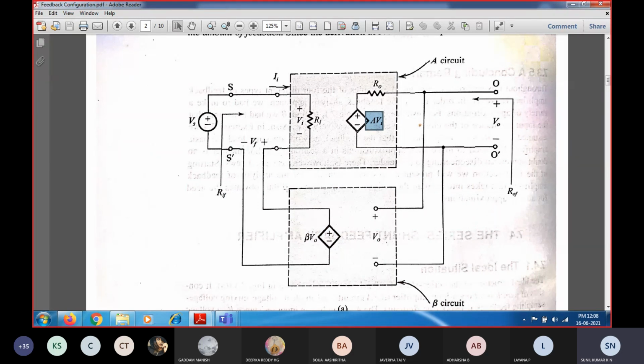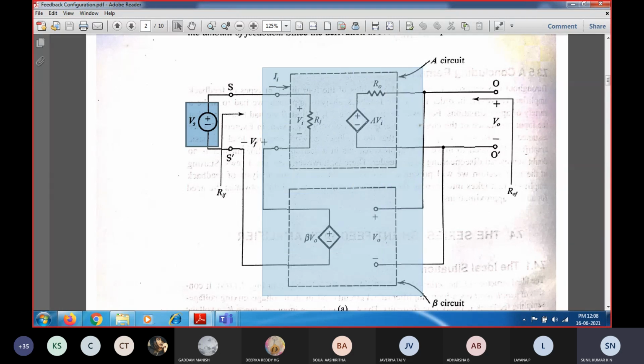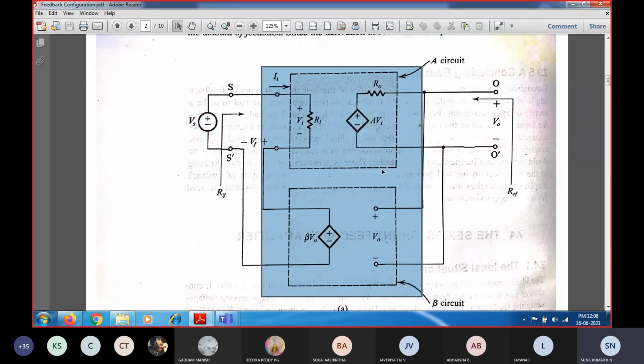Whereas now, if I employ this feedback network and calculate the output voltage to input voltage, the gain we get is nothing but the feedback gain. For this, we are going to write the corresponding equivalent circuit. Whatever A and beta are here, this is the amplifier circuit as well as the beta circuit. So we write the equivalent circuit of this series-shunt configuration and then see what the feedback gain is, that is, the gain with respect to output voltage over input voltage.